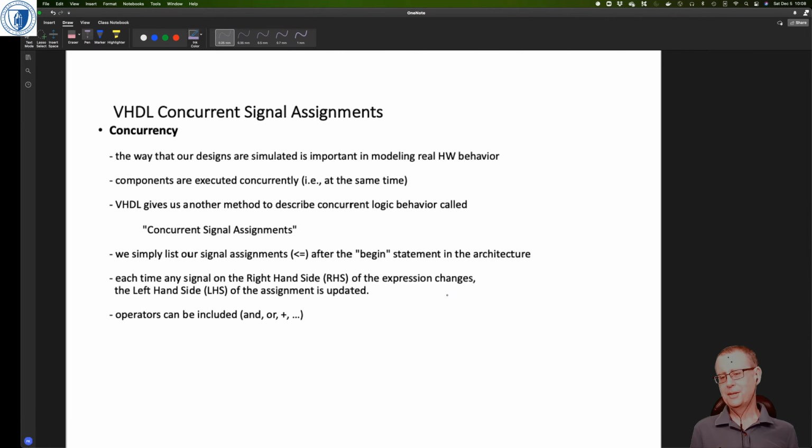One of the really big things for me, and it took me a while to get my head around it last time I took this course, is that every statement in VHDL outside of a process statement is happening at exactly the same time. Just because you've got statements in a particular order doesn't matter. They're all happening at once. It's like you've got a massively parallel machine. It's only once you encapsulate things inside a process statement that you get sequential operation.